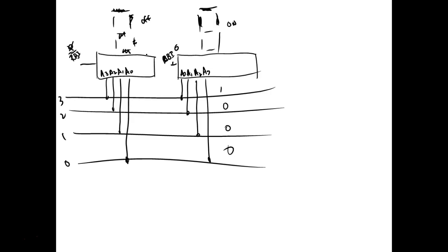And that's because what they're doing is they're using something called multiplexing. So I could come up here and I could have 4 displays or more. And what we would do is each one of them would use its own ripple blanking input. And what I would do is I would only enable one of them at a time. Whatever's on the data lines at that time would be displayed. And then I move to the next display, next display, next display. And it's doing it at such a rate that my eyes never see the LEDs actually turn off and on.